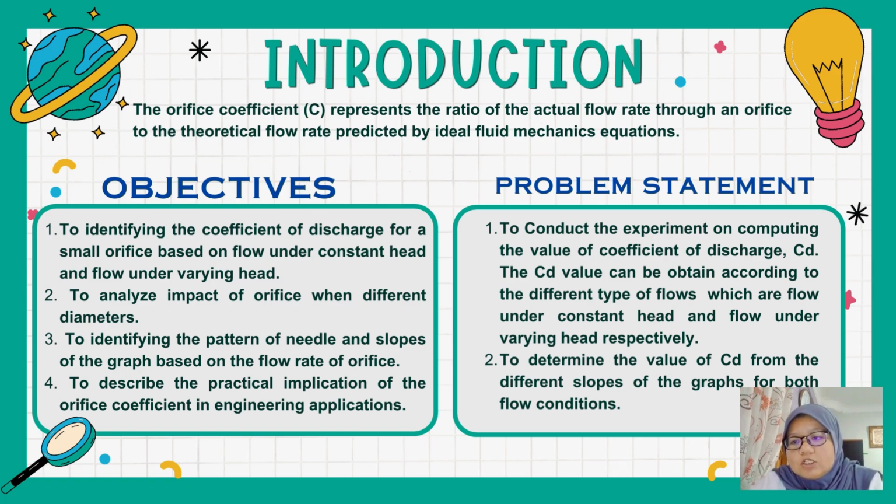The Orifice Coefficient represents the ratio of the actual flow rate through the orifice to the theoretical flow rate predicted by an ideal fluid mechanics equation. The objective of this experiment is to identify the coefficient of discharge for a small orifice based on flow under constant head and flow under varying head.